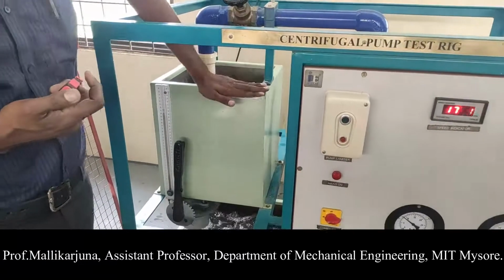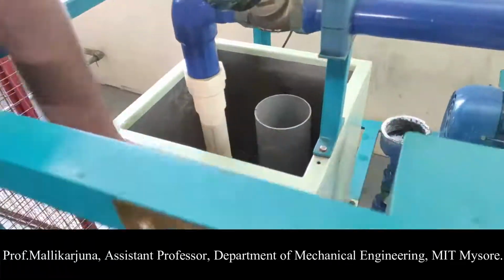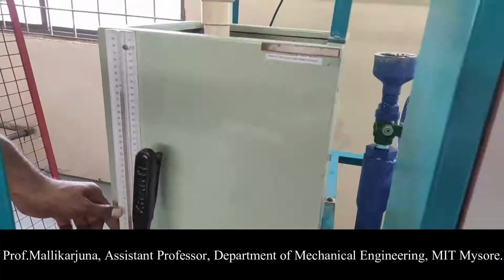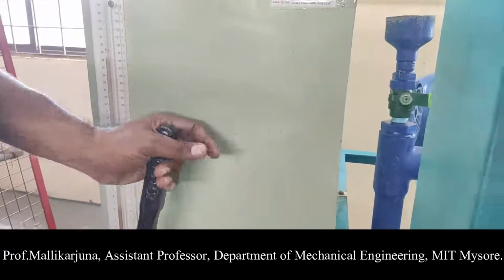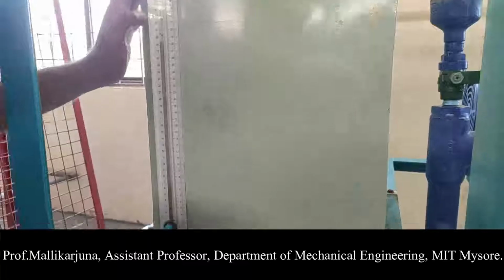This is supplying the water to the collecting tank. On the collecting tank, we have mounted the scale. So this scale is going to show us the reading. So what we have to do is we need to close this valve. For a fixed rise, what is the amount of time taken?